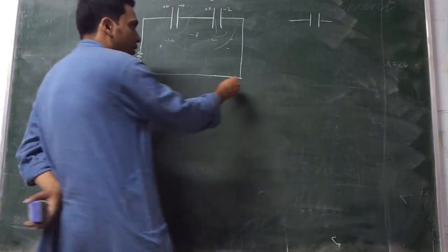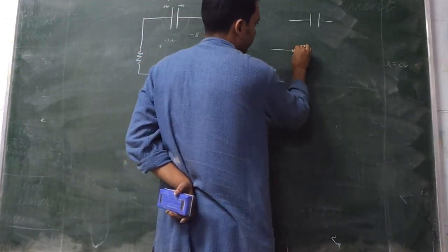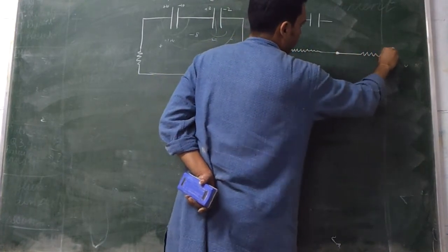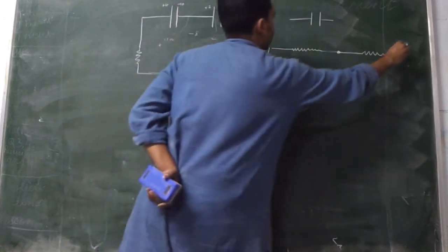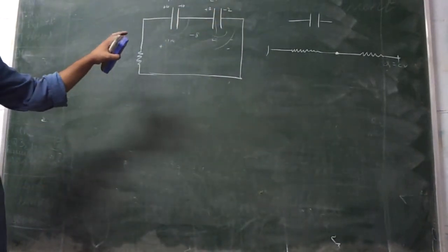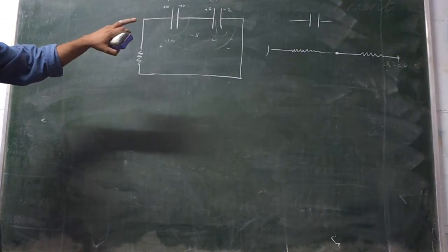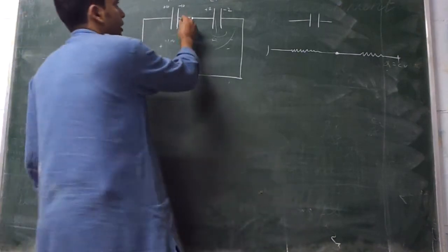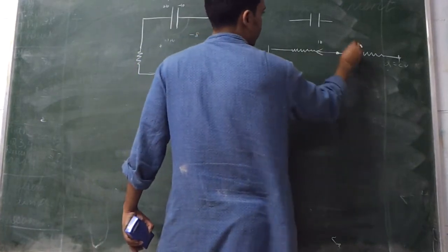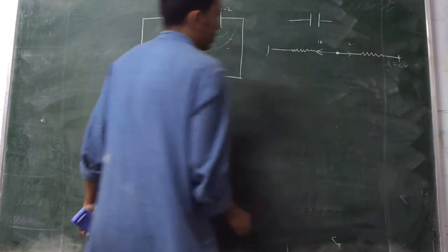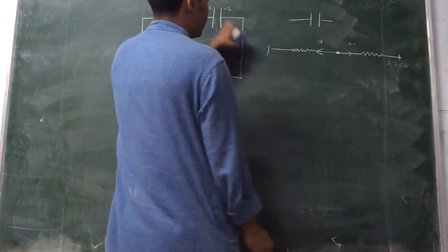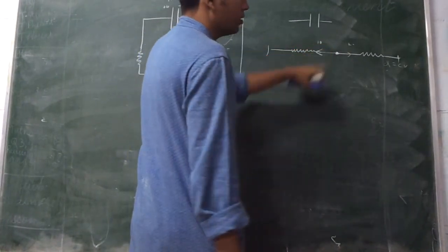What is physically happening over here is, these two capacitors are like two strings. They have different voltages on them, so they have stretched to different forces. The voltage is the same as the force. This is 10 Newton force and that is pulling with 2 Newton force. So what will happen is, this will stretch more, that means charge will come on this such that the forces balance.